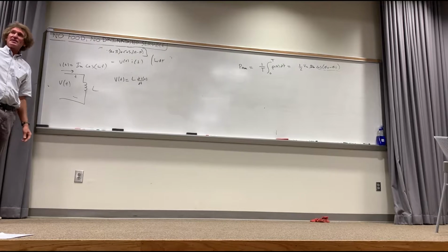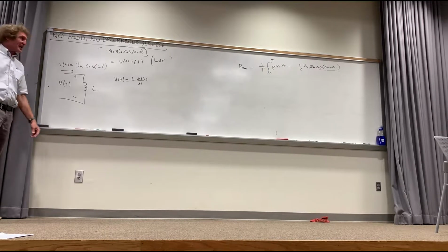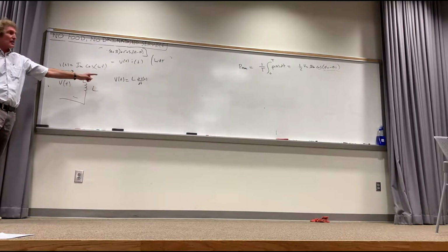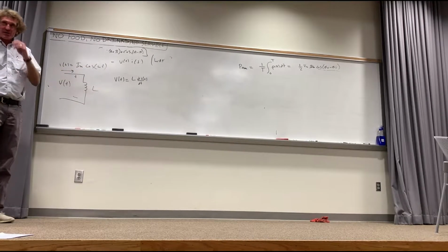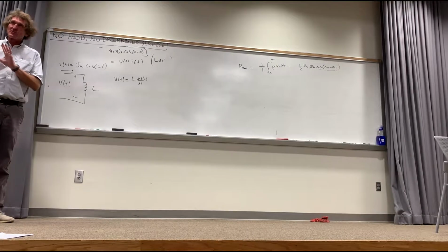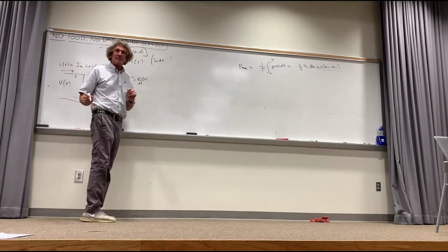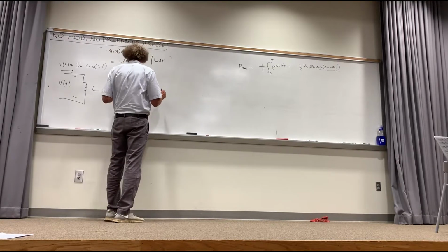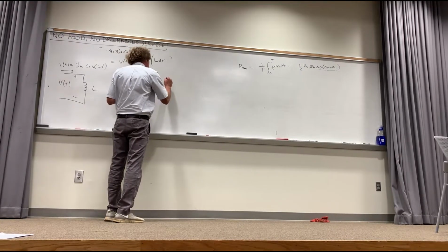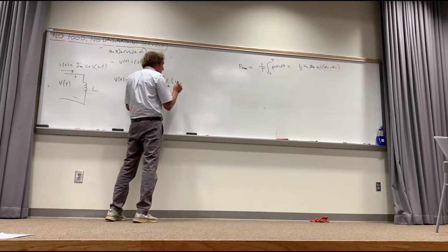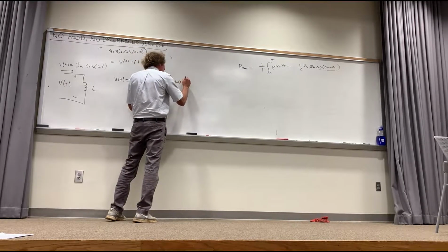Here, it's L di dt, it's the rate of change of the current times L that gives you the voltage across that inductor. I don't want to complicate this too much, but I do want to say one thing. Actually, this is an assumption that the inductance is not time varying. The actual value of that voltage across there is equal to the derivative with respect to t of the quantity L, which could be a function of time, times I of t.